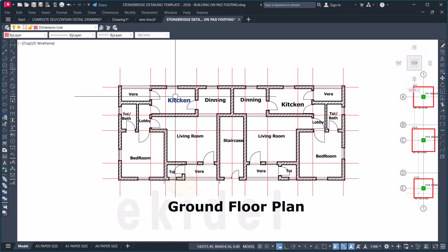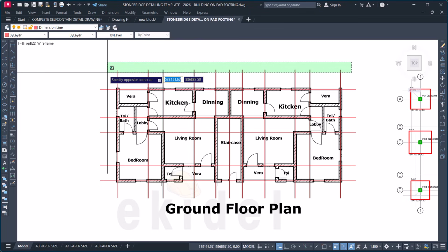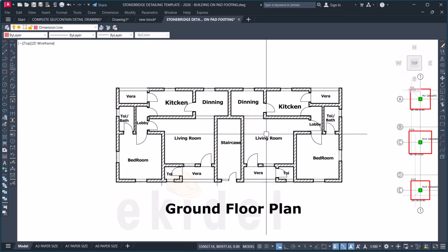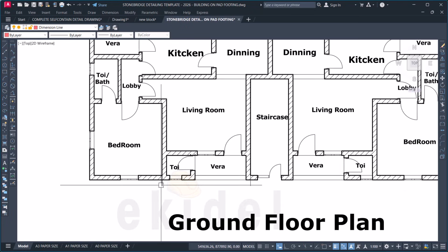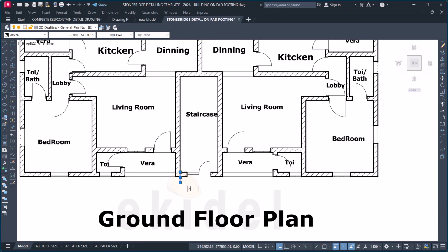So we are left now with our grid points and our block walls. Now I will also remove all these grid lines which I used. So I'll take off these grid lines now and just have my block walls alone. Now you can see the block walls, the door symbols, and everything. This is how the architectural drawing came to us. So this is what we are going to use to prepare for our foundation layout.